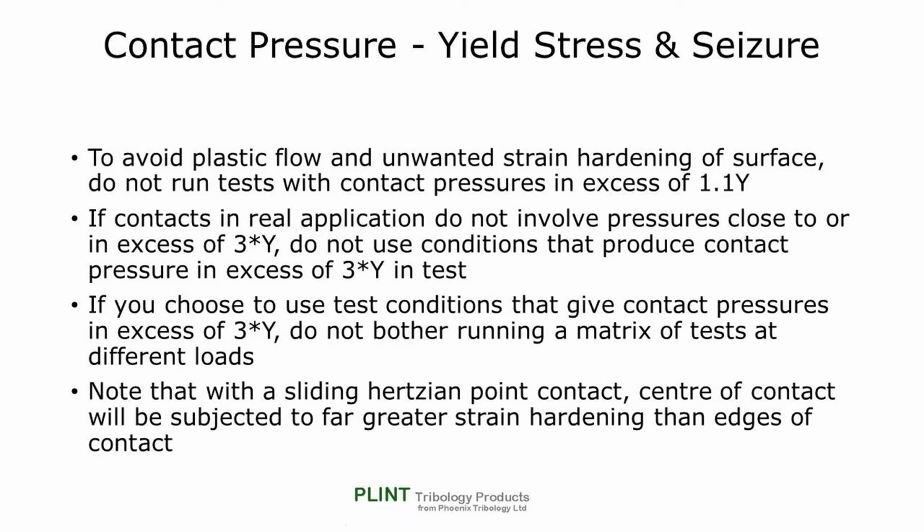If we now add mechanical shear because of sliding action, we would expect a further decrease in either the applied load or the temperature at which yield occurs. The upshot of all this is confirmation of the general pointlessness, pun intended, of running a matrix of tests with a ball on flat specimen configuration starting at different loads. We learn nothing if our test simply produces the same result regardless of the test conditions.